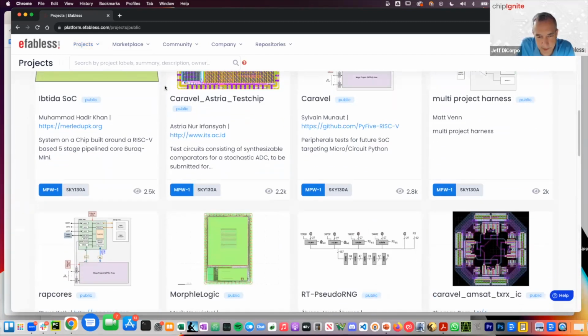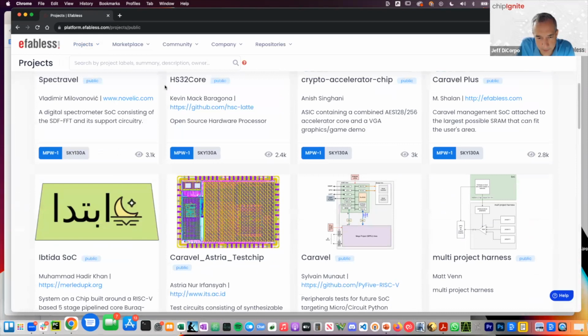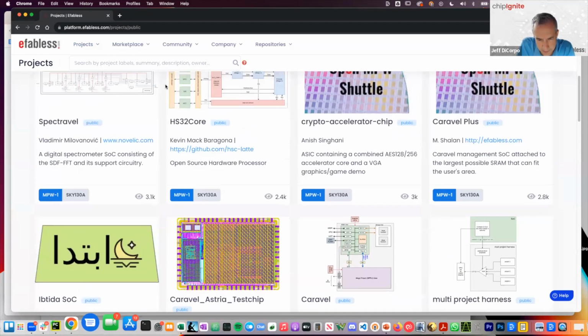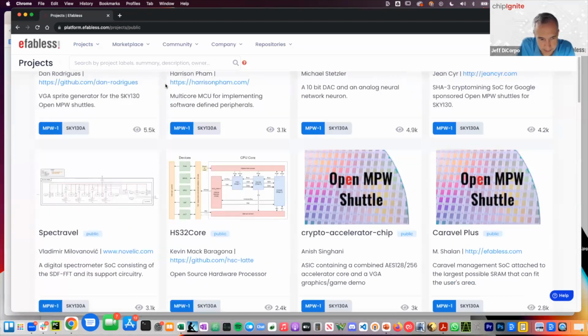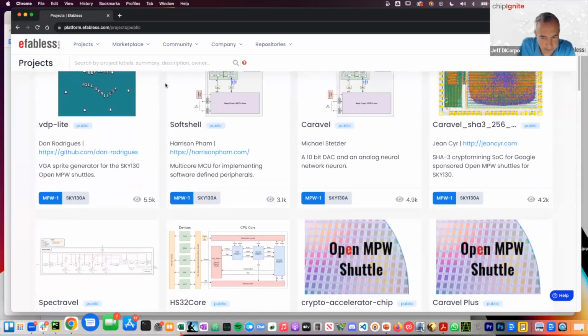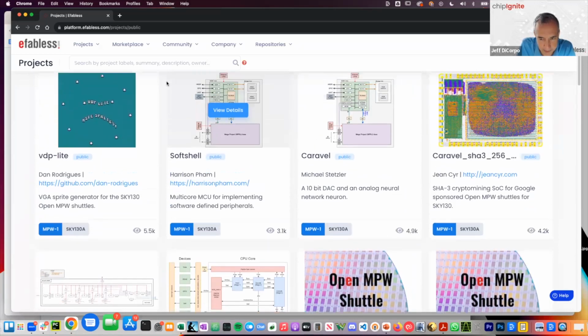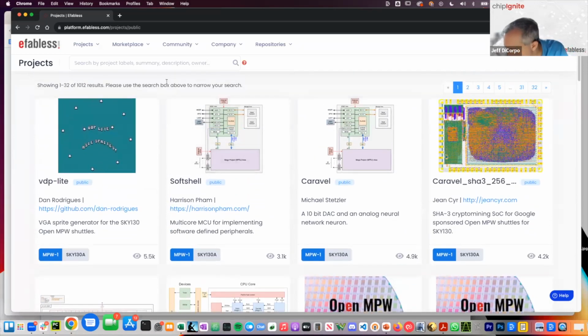A number of these have implemented SRAM using an open RAM macro that's available publicly. We also have a DFF RAM macro that provides a synthesized memory macro that is also an option that you could implement. And I think the other question is any estimates on the possible capacity, roughly.